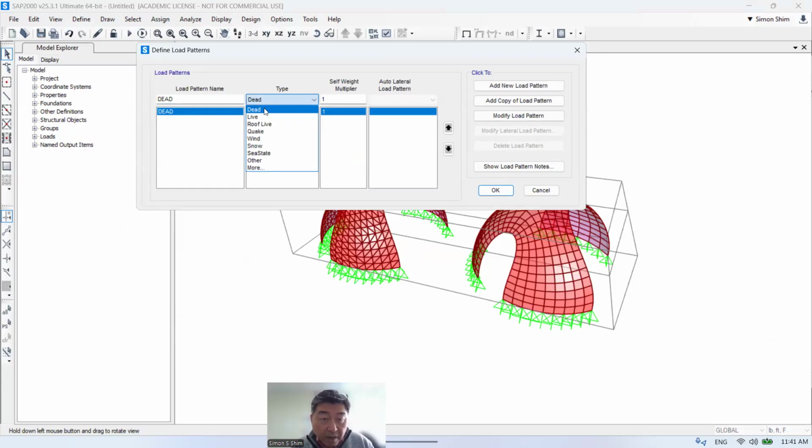We're going to keep it. What we are interested in is the self-weight of the structure. We don't want to calculate the self-weight manually. ETABS or SAP knows it since we defined the geometry and slab thickness, right? We assigned a 6 inch slab.